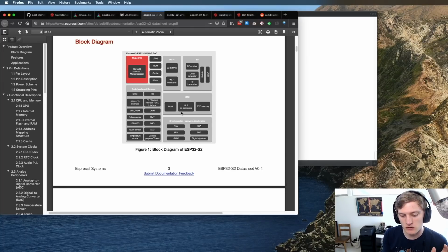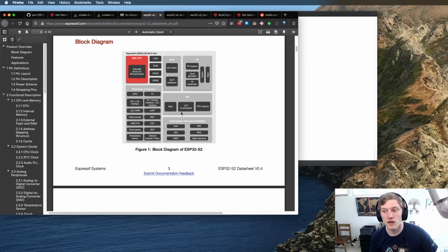That's not so much an issue on the SAMD21 and maybe even the 51, although the 51 is on that gap. The SAMD21 is 48 megahertz and the SAMD51 is 120 megahertz. And that's right around the cusp, I think, of how fast flash gets. After that, you kind of don't benefit anymore. Something that's been true for these ESP chips, even from the ESP32-S2, I believe, is that the cores are quite quick, but the memory isn't necessarily, especially when it's external.